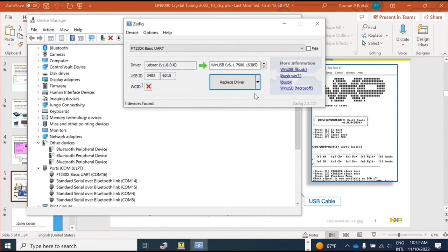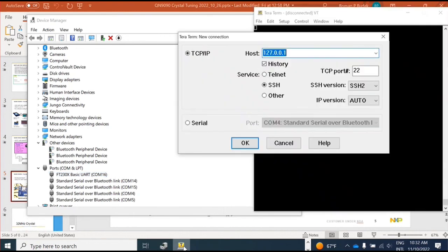So now that I've loaded all that, I would go ahead and load my terminal emulation, TeraTerm. Now it works with a TCP or a serial port. Remember what I said is that we're using a serial port driver emulation from USB. I can get what port it is. It's COM16. It'll keep incrementing every time you use the cable.